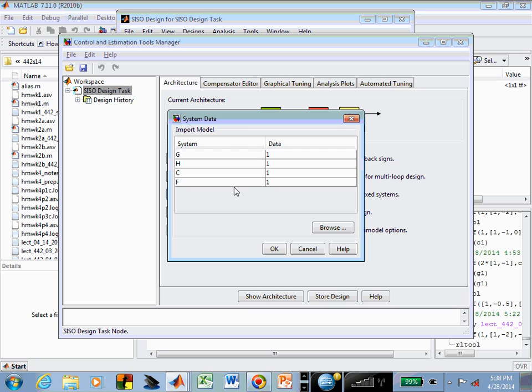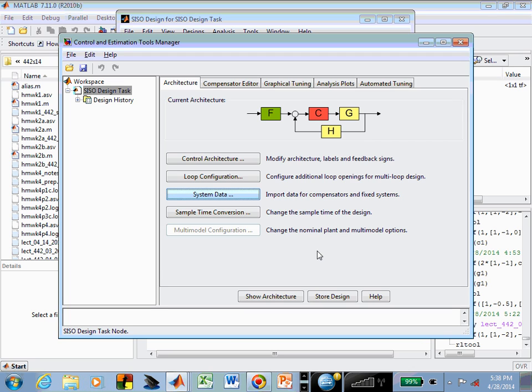and before we do, you have to memorize this block diagram. Our plant is G. We're using unity output feedback, meaning the H is going to be 1. We're not going to have any feed forward gain or reference input gain. Our F will be 1, and we'll be playing with putting poles and zeros, sprinkling those down in the C, in the controller.